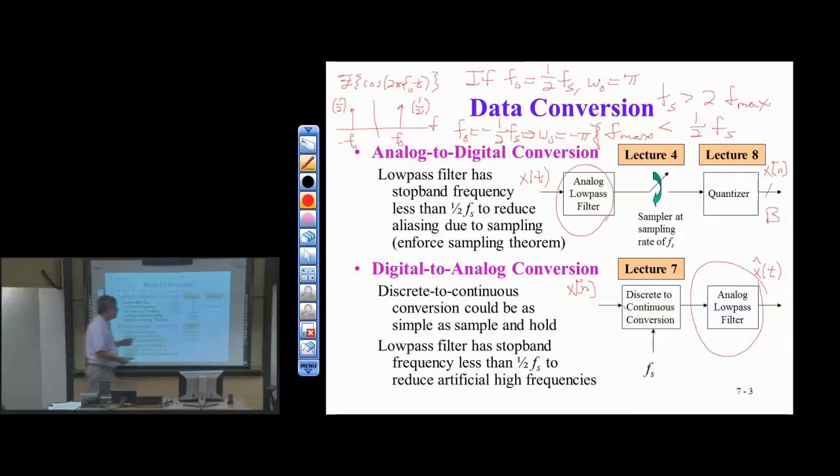Now these two analog low-pass filters have very similar design considerations, and you could really reuse. So again, it depends on how much work you put in here. So if you don't do much work on this discrete to continuous time conversion block, then you can simply reuse this analog low-pass design. If you want to do more work in the discrete time to continuous time conversion step, in fact, if you do enough work, you may not even need the analog low-pass filter, or it won't help you, or you need a very simple biquad or something. You don't need something too involved.